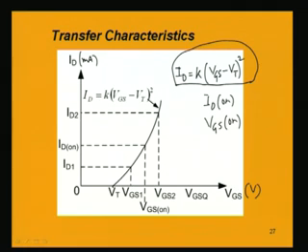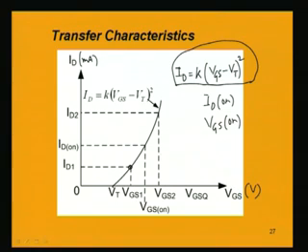So, let us do that. Let us take any other value, say VGS1, and find the drain current, which is ID1. So, we are getting another point here. Again take a VGS for a current in the higher region, say a higher value of ID2 is given for VGS2, that is another point. So, we have 4 points right now. Joining these 4 points, we get a curve which is the transfer characteristic for this enhancement type MOSFET device.